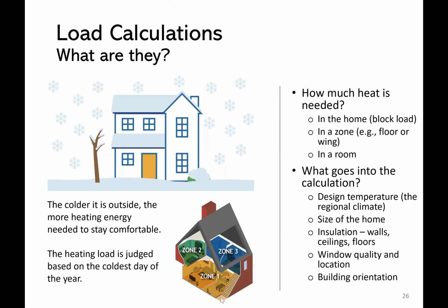To calculate a home's annual heating load, binned weather data is used to determine how much heat is required to heat a home for an entire year. Load calculations can be performed for an entire house or various parts of the house. When a thermal load is calculated for an entire house, it is referred to as a "block load calculation."